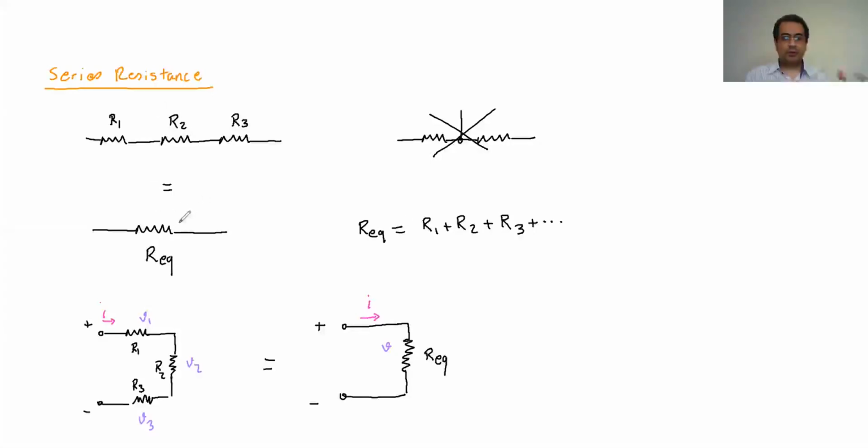Replace them. So when we are analyzing the system, if you have resistance sitting in series, to simplify our circuit, we just replace them with the single equivalent resistance, then solve it, and then we bring the I back to each of those original elements, and then resolve the circuit for those original elements.